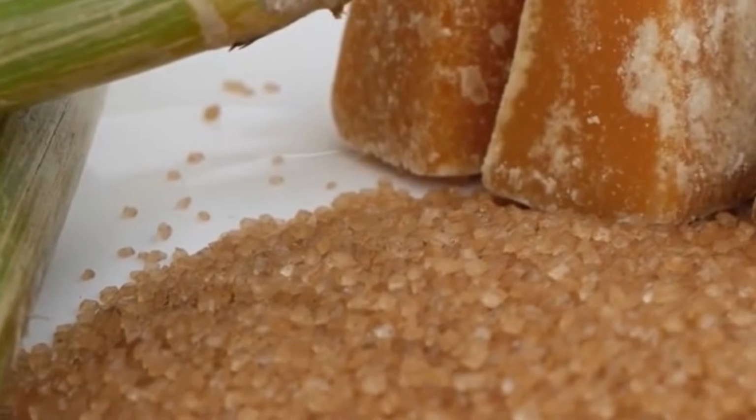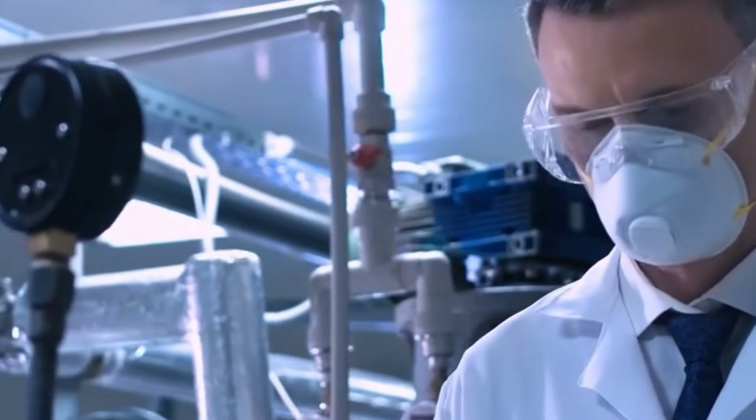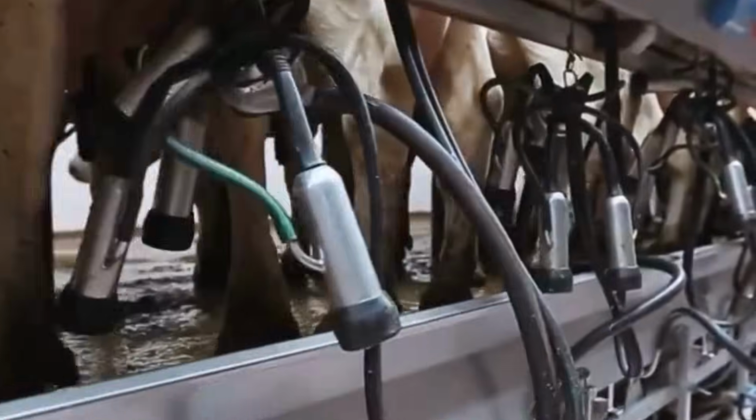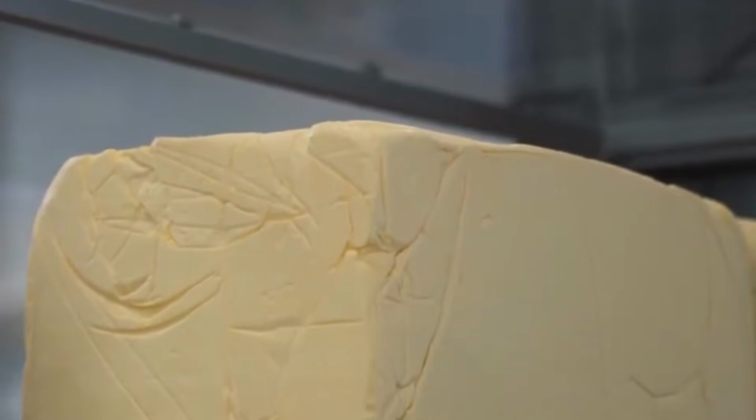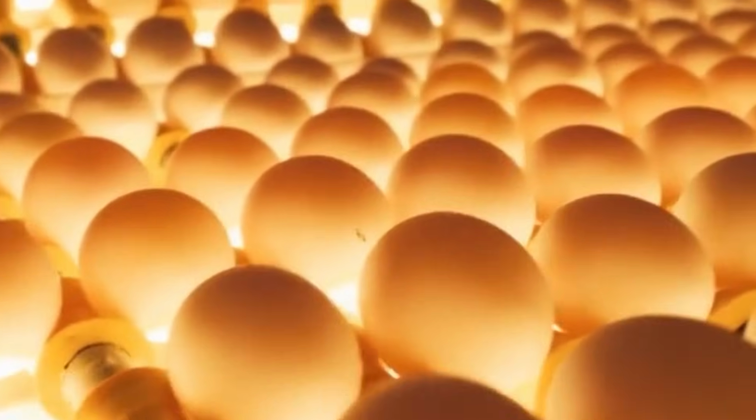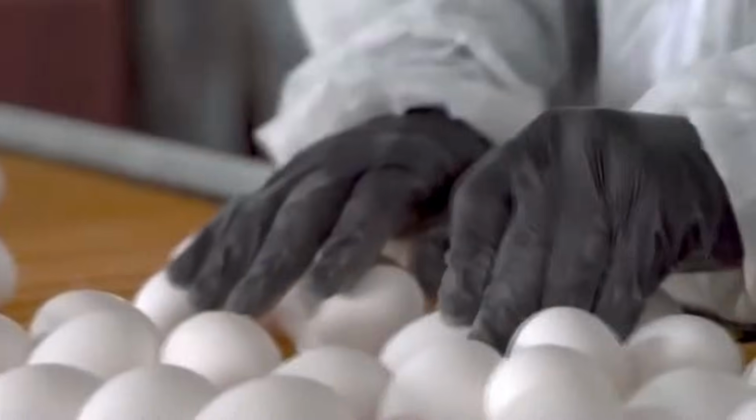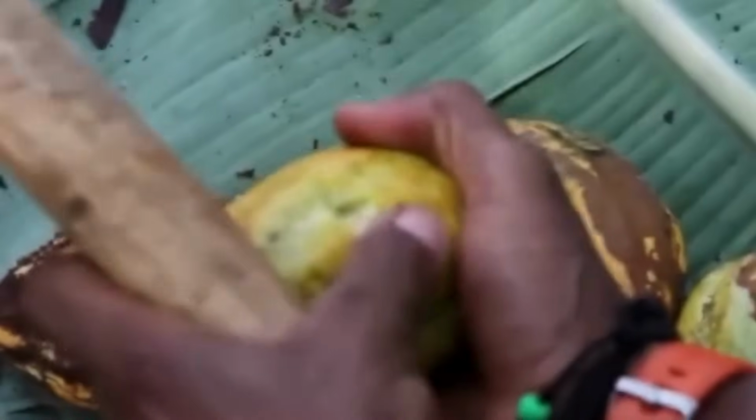Palletizer systems incorporate automatic pallet dispensers and slip sheet feeders. Gripper heads are interchangeable for different case sizes and stacking formats. Production data, including line speed, output volume, defect rate, and downtime, is continuously recorded and transmitted to a manufacturing execution system. Reports are generated hourly for supervisory review and performance tracking.